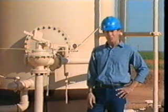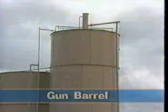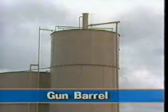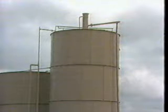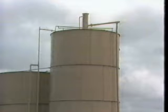Devices such as gun barrels and free water knockouts are used to treat emulsions. A gun barrel is a settling tank which separates oil and water in the field. After emulsified oil has been heated and treated with chemicals, it's pumped to the gun barrel for gravity separation. Gun barrels are still common, especially in older fields, but they're frequently replaced by heater treaters.